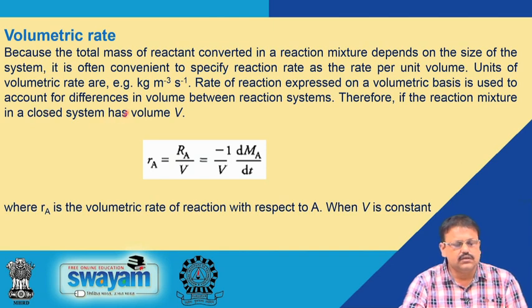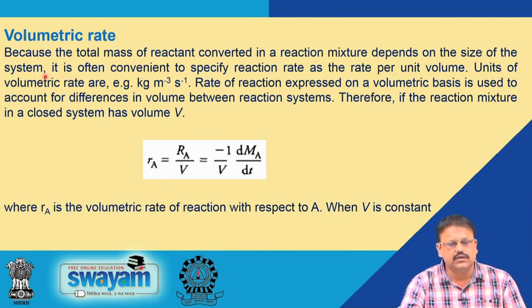So the total rate is nothing but the total production rate of a plant, in specific examples. The volumetric rate is used for designing any reactor: per unit volume, how much mass is converted to product will be calculated. As per the requirement of product, the volume of the reactor can be designed.